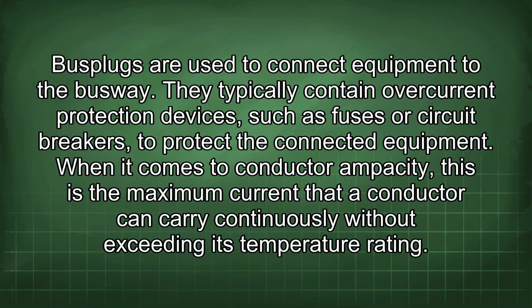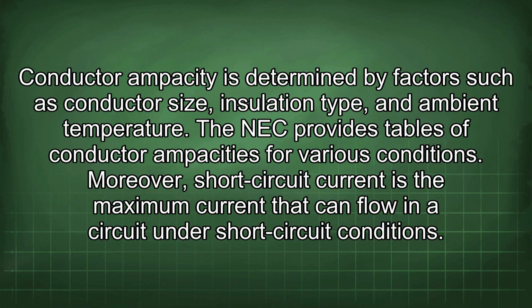When it comes to conductor ampacity, this is the maximum current that a conductor can carry continuously without exceeding its temperature rating. Conductor ampacity is determined by factors such as conductor size, insulation type, and ambient temperature. The NEC provides tables of conductor ampacities for various conditions.